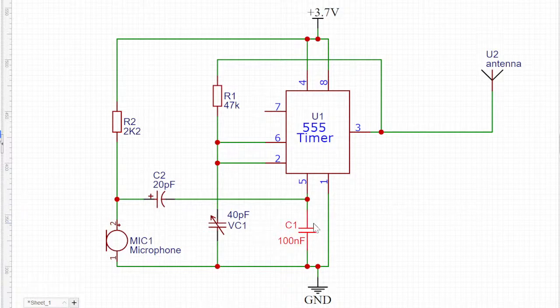Try to use this capacitor here and try to amplify this. Now, you can just use this directly to drive a speaker. So you can connect a capacitor here at the output. So let's just clone this one here. You can connect a capacitor here and then connect a speaker at the output here.